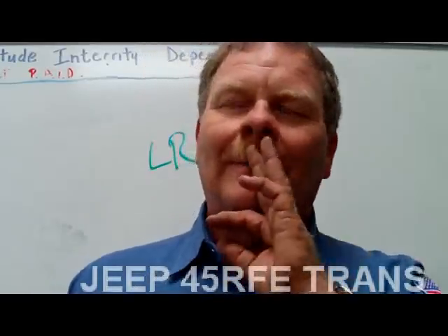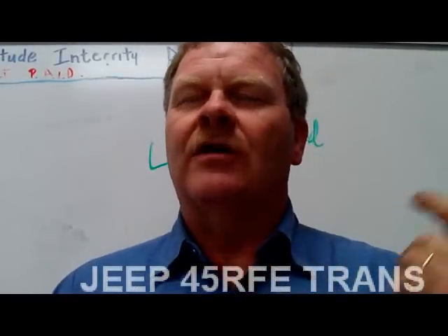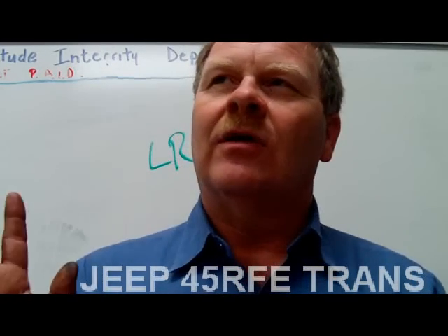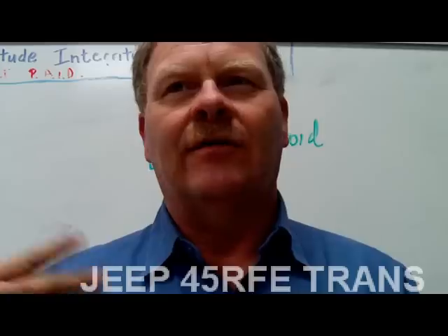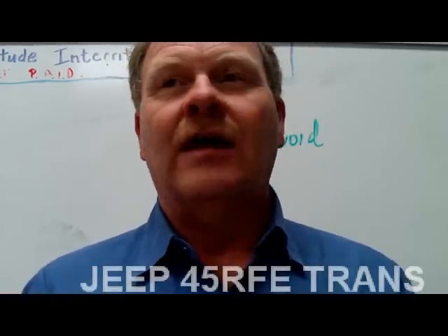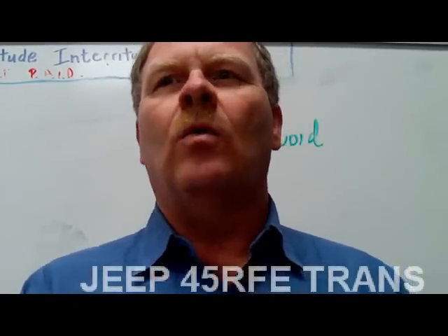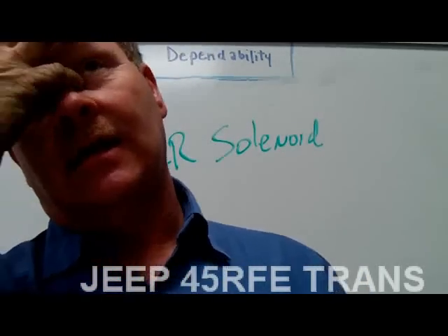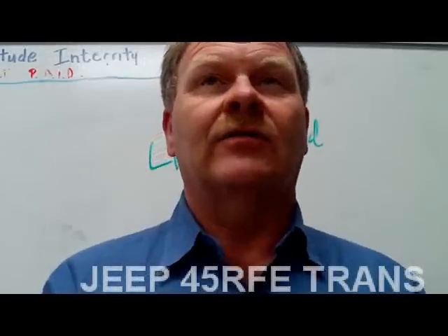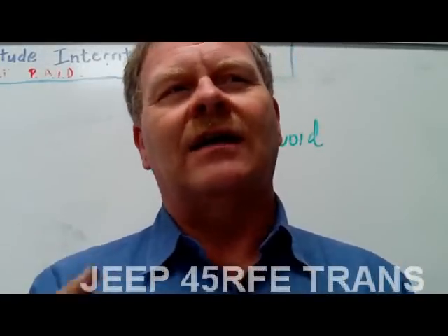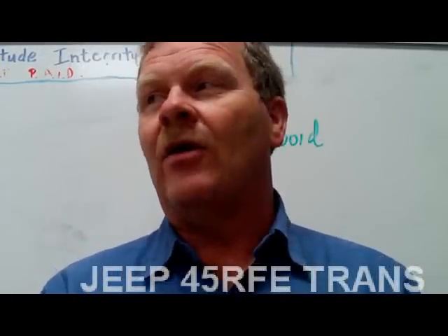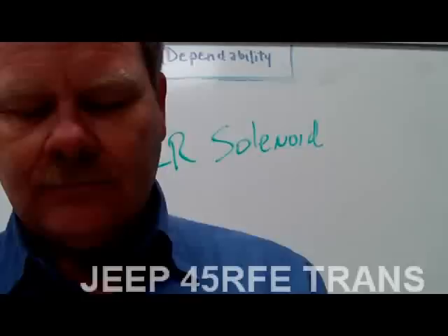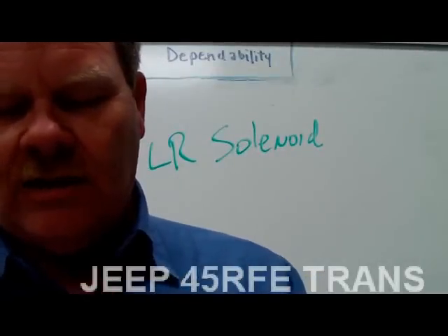Michelle Goolsby's car had a wire harness that was shorted going into her electronic throttle body, and it would turn on the wrench light, and she would only have capability for half throttle. They were afraid that if it didn't know what was going on between the accelerator pedal sensor and the throttle body via the PCM, it was going to run away. So instead of running away, just to make sure nothing goes bad wrong, it limits her to half throttle. So anyway, the 4RFE transmission is going to be serviced only as an assembly.